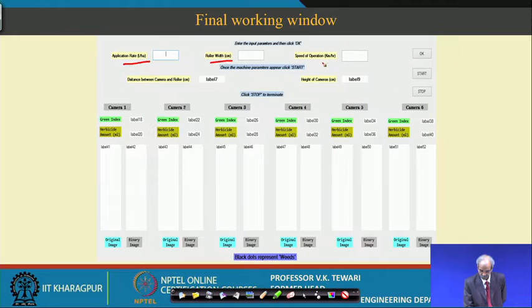Speed of operation is another parameter which needs to be maintained and controlled. If you are moving at a very fast rate, the amount of chemical which oozes out onto the weeds will be lesser. At the same time, because of the higher speed of rotation and the centrifugal action of the roller, a lot of chemical will be thrown off, and it may not go onto the weeds but onto the cover and go to waste. That is why we would like a proper speed to be maintained.